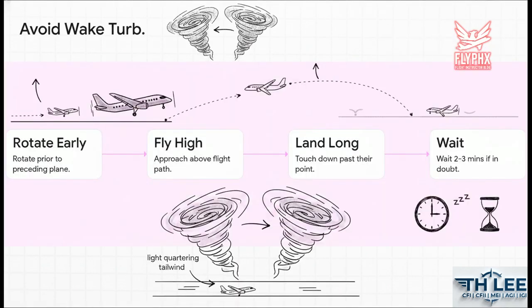But listen, those wingtip vortices aren't just some cool aerodynamics concept. They are a severe invisible hazard known as wake turbulence. The most dangerous wake turbulence is generated by aircraft that are heavy, clean, and slow. To avoid getting totally flipped by the wake of a preceding heavy jet, you have to memorize these steps to fly in the bowl. Always rotate for takeoff prior to their rotation point.